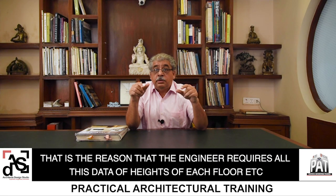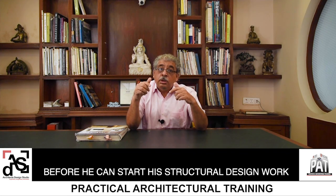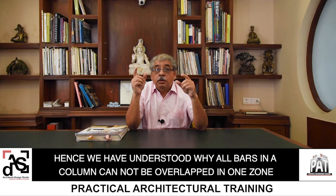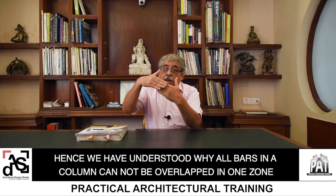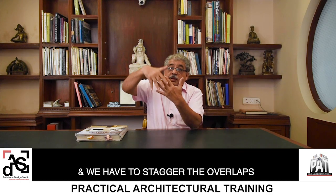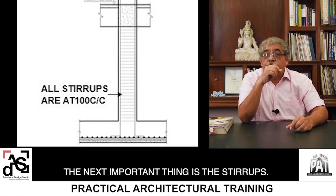That is the reason that the engineer requires all this data of heights of each floor before he can start his structural design work. Hence, we have understood why all bars in a column cannot be overlapped in one zone, and we have to stagger the overlaps. The next important thing is the stirrups.